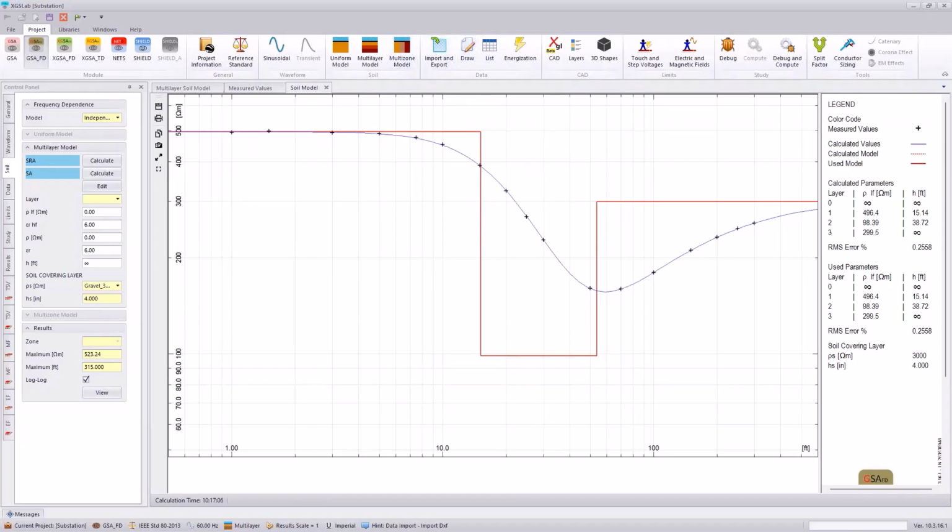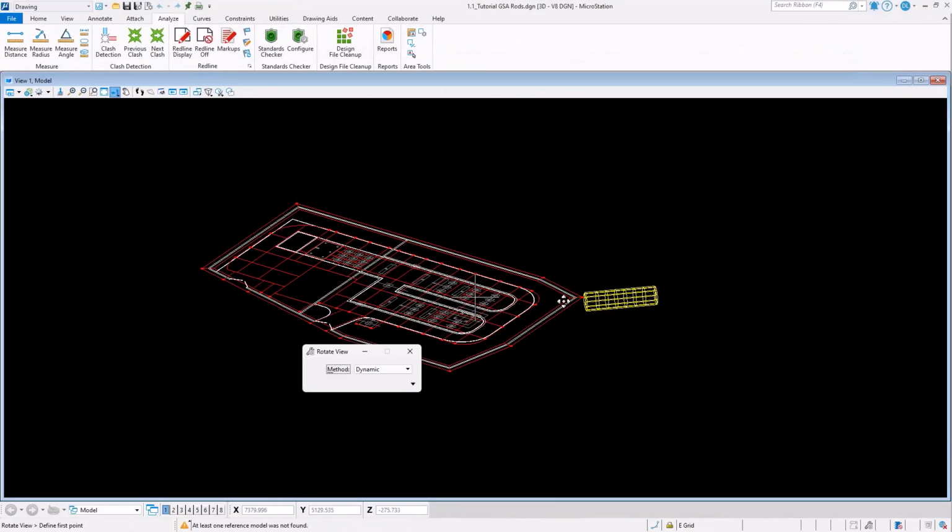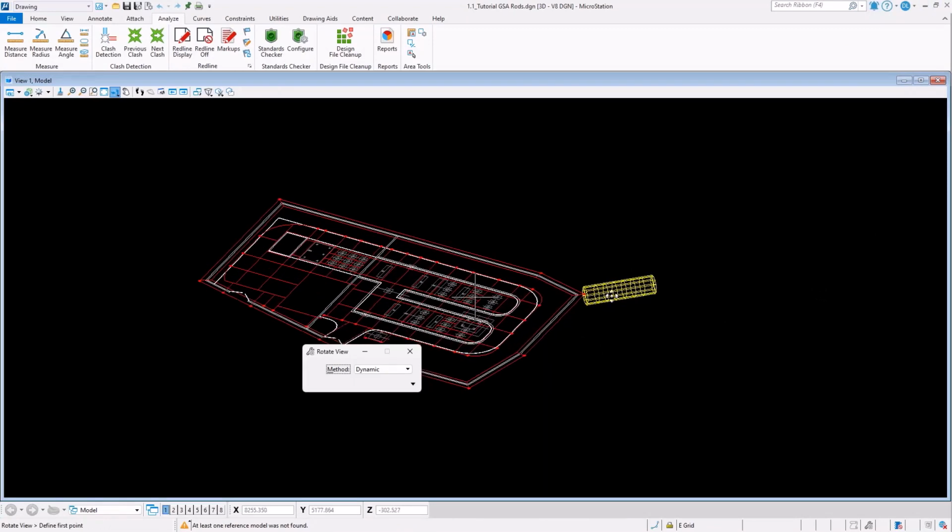Next, we need to pull in our grounding system, energize that, and see how much voltage is transferred to our external tank. And what we're really concerned about is touch voltages of something on this transferring from our substation.